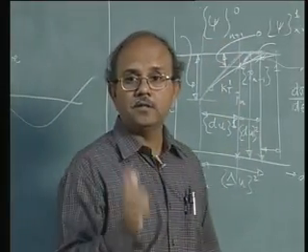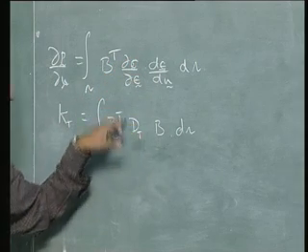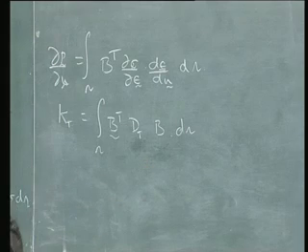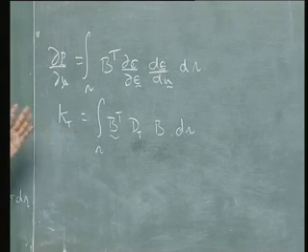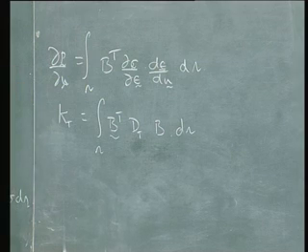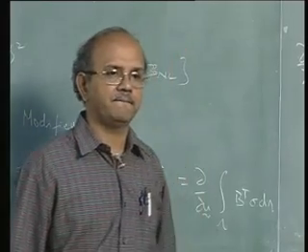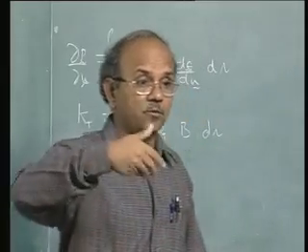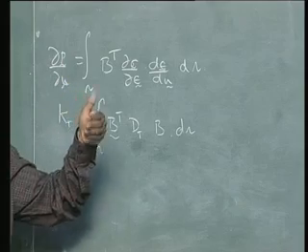So what is most important in this case is that we have to have this ∂sigma by ∂epsilon, and this Dt definition is what is important. In fact, for any material, suppose you have a new material, and if you are able to define this ∂sigma by ∂epsilon, why I put ∂sigma by ∂epsilon is basically because sigma can also be a function of, say, the damage parameters and so on, in which case I can't write it so nicely. It's always important that you realize what you are writing and what assumptions are involved. Sometimes this sigma may be a function of epsilon and, say, a damage parameter d.